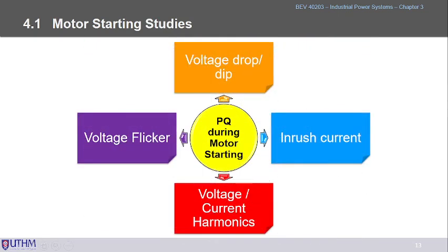And what we can expect from motor starting regarding power quality. First you will incur voltage drop or voltage dips. Okay? Once it draws so much starting current, our voltage will experience some dips. And of course the inrush current, sometimes we call it a transient, and the transient currents. And the voltage and current harmonics also, especially when we use converter types of starting methods, like the frequency converter start.